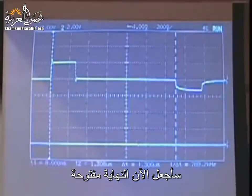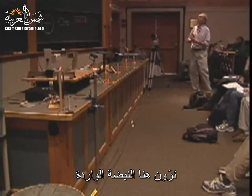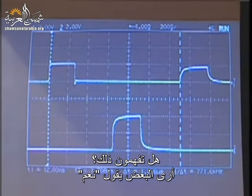But now, I'm going to make it an open end. All right, so here we see the incoming pulse. And you see the one that comes back is now 1.29 microseconds, big deal. A mountain comes back as a mountain, but now there's something very interesting. At the end of the cable where it is open, you see twice the voltage. Do we understand that?